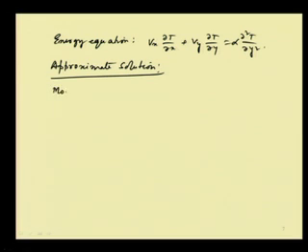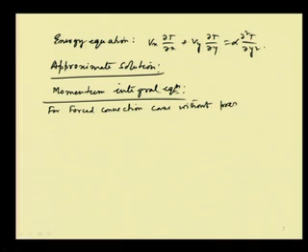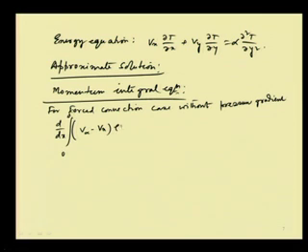Okay. So, if we try to see the momentum integral equation, that we already have seen for the forced convection case without pressure gradient. We have seen that d dx of integral 0 to delta rho Vx into (V infinity minus Vx) dy is equal to tau w.